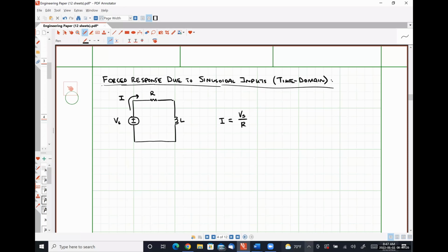Vs over R. So I really like the way that you phrased your answer there. Mr. Rayford said that since it's a DC circuit, our current I would just be Vs over R. So what you have unknowingly done is exactly what I'm talking about here, okay? In a DC circuit, we expect to get a DC response, right?